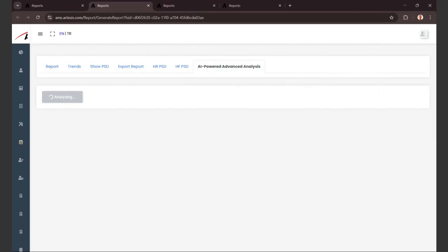I mean, the bar graph already shows there's a rotor issue which is close to red level on the bar graph. But let's see what the analysis is going to tell us. And sometimes the auto analysis might not accurately identify the severity of the problems.